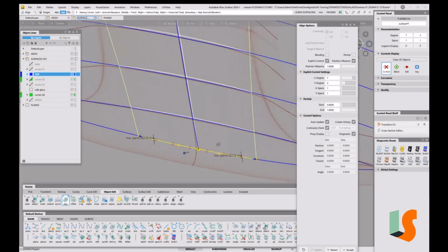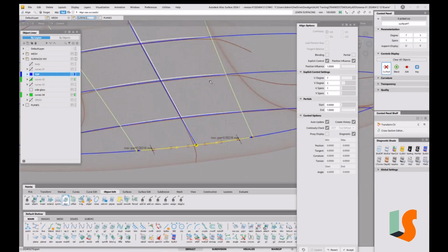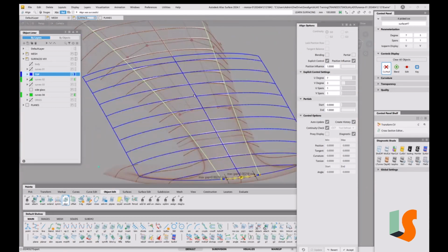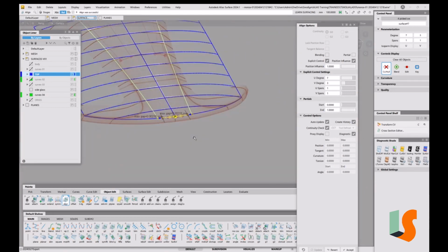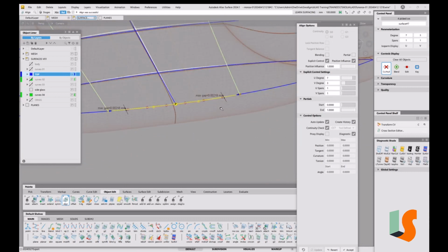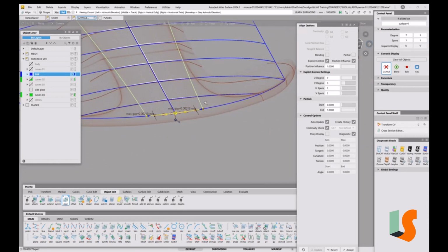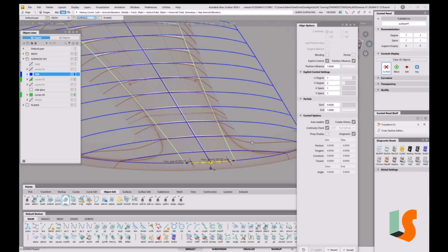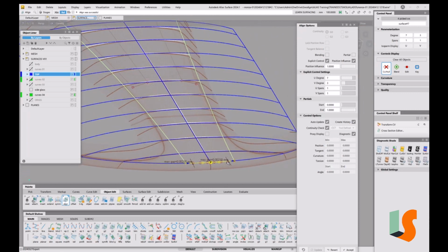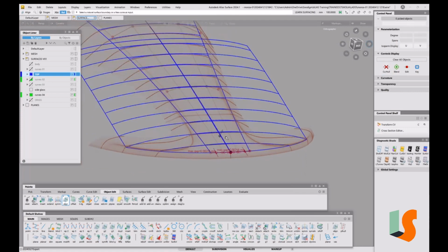Now we don't need this 100% because this is all just to try and get these surfaces coming together. We've got a maximum gap of 0.002. That's more than close enough for what we're doing at the minute, because I'm not trying to get that to that back edge. I'm actually going to trim convert it back at some point or do something with it. I'm not actually going to take it all that way. So we'll do that. Now I'll take history off as well. I don't want history on. I don't want that changing anyway. Just want to keep it as it is.